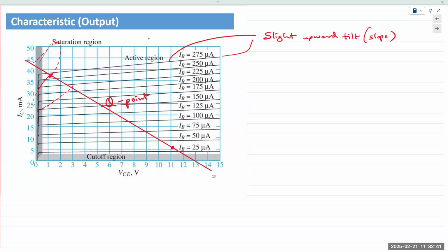The reason I'm going over this is because we'll use this technique to design your amplifier for Lab 8. Well, there are two different techniques. You can use analytical equations, and you can also use graphical load line techniques. As I said, we'll look at it later on in this chapter. But you will use that technique to bias your amplifier circuit for Lab 8.